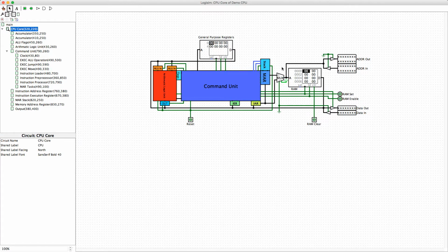a load or store instruction was supposed to load what was in the instruction address register directly into the RAM. That didn't work out. Previously, it would just load the instruction address register, then load the results into the memory address register, set the return address, then load the return address when we were done with loading and storing data. But this, what I thought would be a small change in the architecture, turned out to be a CPU breaking change. It no longer works for any of the instructions, at least not that I can tell.